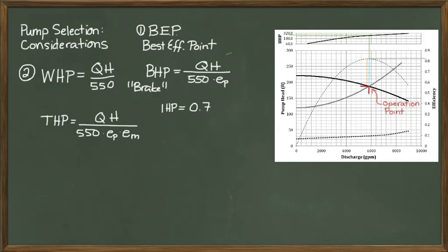And this is helpful for us because we want to know how much power is required to operate a pump. For every 1 horsepower, we have 0.746 kilowatts. And for those of you who pay power bills, know that our energy is billed to us in kilowatt hours. So this will give us a tool for determining what is the cost of operating our pumps.